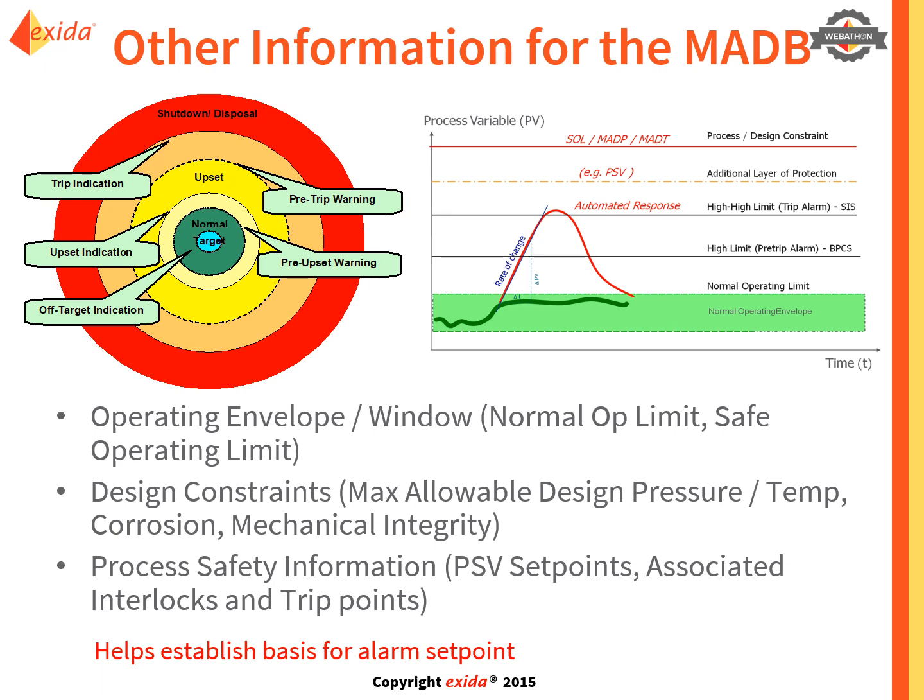But if the operator needs to reset the plant and get it back online in a timely fashion to avoid excessive financial losses, then that could be considered an alarm, because he has to carry out a response. So that means that you would want to add an alarm, and this is useful information in deciding that. Now, these deviations from the norm and their extent can be very useful in other additions to the master alarm database.